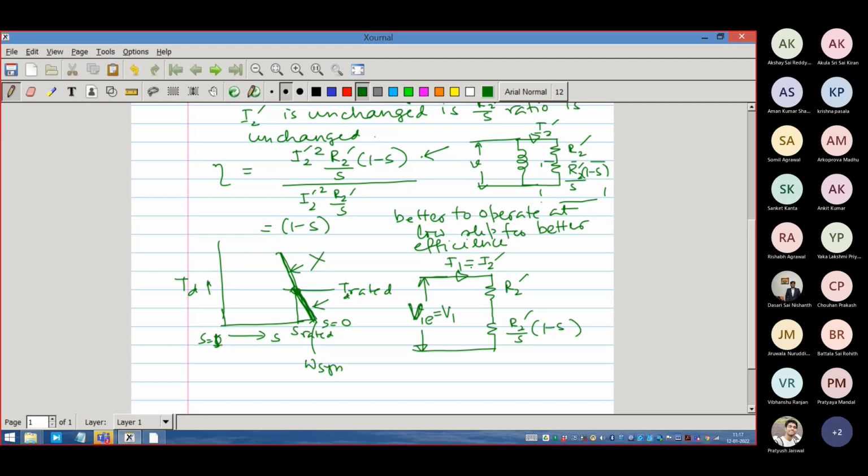This is the model of the electrical machine when we are using the machine as an electronic drive, right? What is the difference in an electronic drive? I will be able to adjust this voltage. In the normal conventional machine, I will not be able to adjust the supply voltage. Here, I would have the ability to adjust the supply voltage.